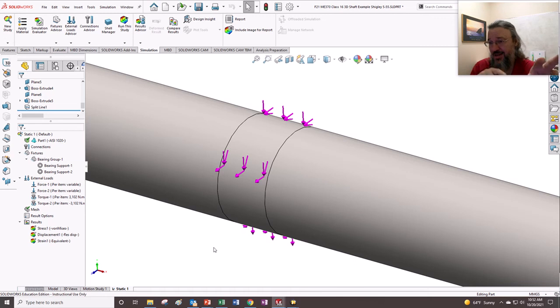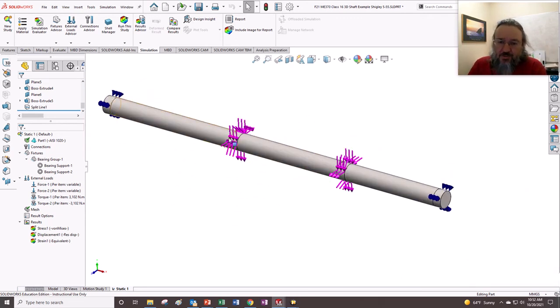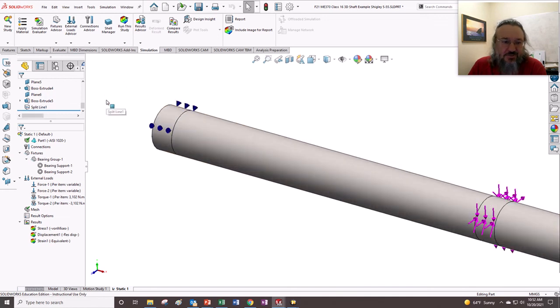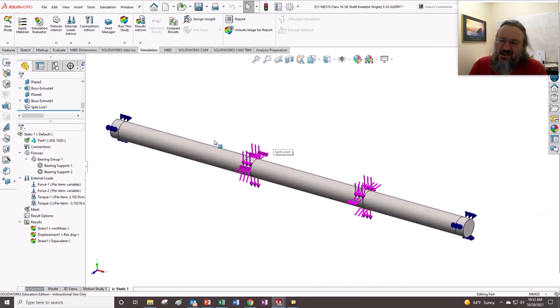Even though you made them the exact same numbers right in here, it's by way of this matrix needs to be able to be solved. Okay, so just be on alert that you might actually need to trick it sometimes by holding one node in the rotation, like at the end, just to keep the thing from exploding, because it might divide by 0 somewhere and get all angry at you. These kinds of things, but they probably built some stuff.